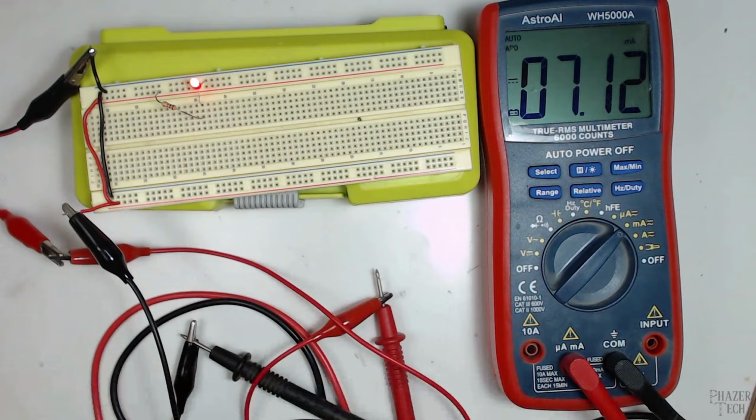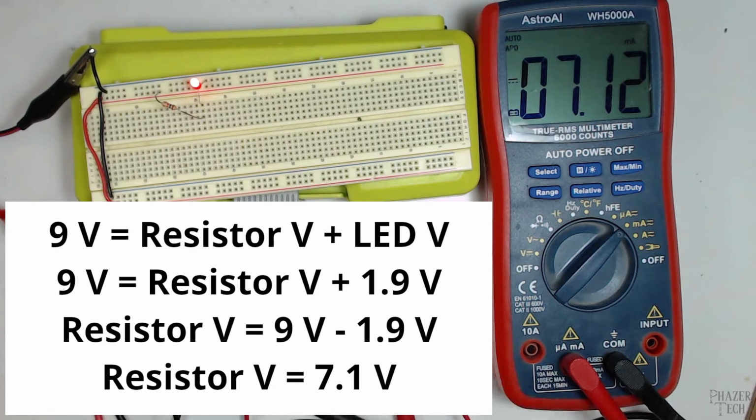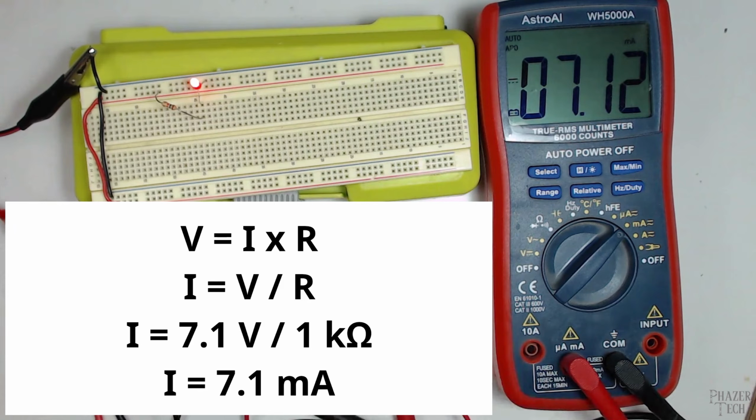In the last video I used a 1 kilo ohm resistor and we found the total current to be around 7 milliamps by measuring it with a multimeter. But now let's find out how to calculate this without measuring anything. First, we have a 9 volt power rail, which means the total voltage across the resistor and the LED needs to add up to 9 volts. We know the LED has a forward voltage of 1.9 volts. So now we subtract 1.9 from the power supply's voltage in order to get the voltage drop across the resistor, which is about 7.1 volts. Now we can calculate the current since we know our resistor has a value of 1 kilo ohm. This comes out to 7.1 milliamps, which is exactly what we measured it to be in the previous video.